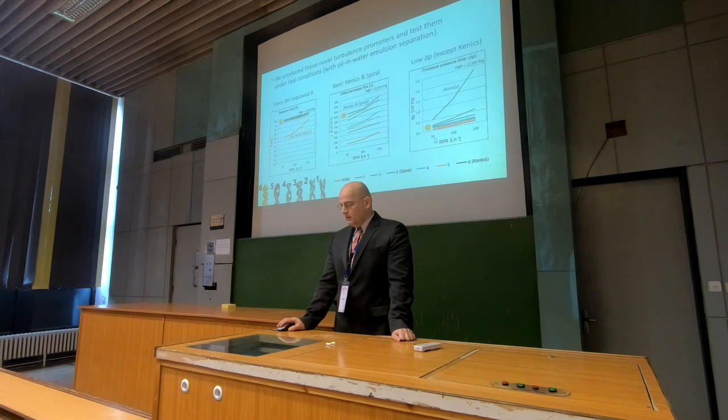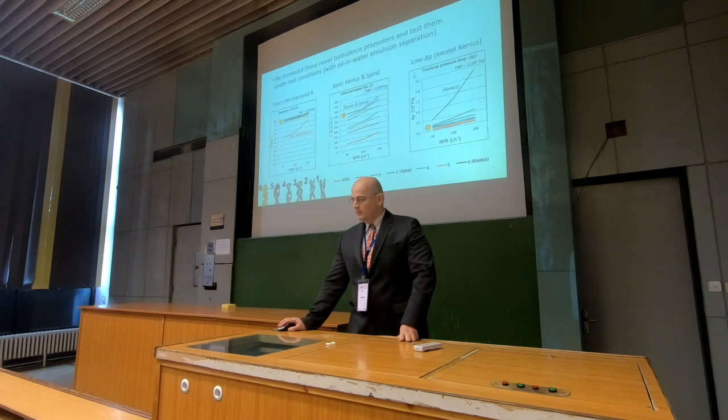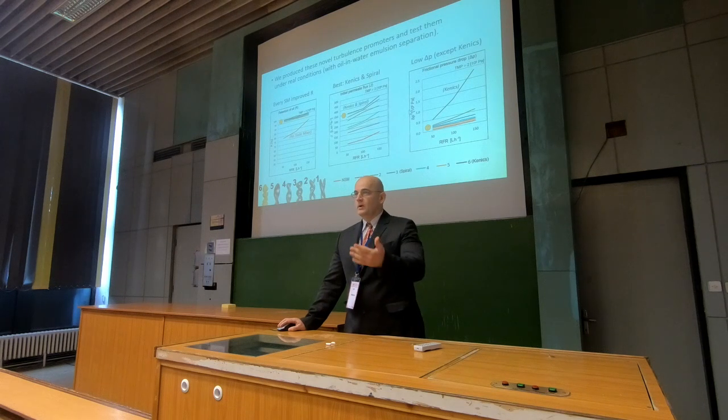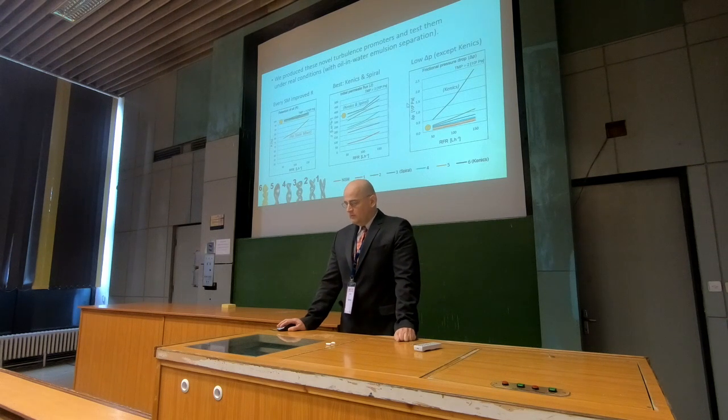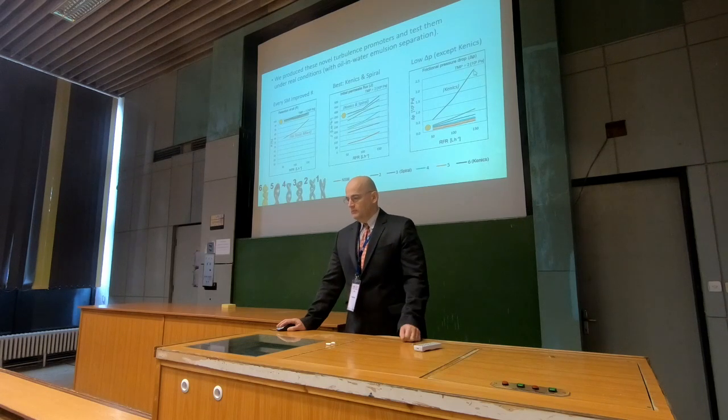And the third, as a function of flow rates, the pressure drop along the membrane. So this is why we were searching for new geometric shapes. You can see almost every new static mixer, and of course the empty tube, have the lowest effect on the pressure drop along the membrane, and the Kenix static mixers, especially at higher flow rates, have much bigger friction in our case.